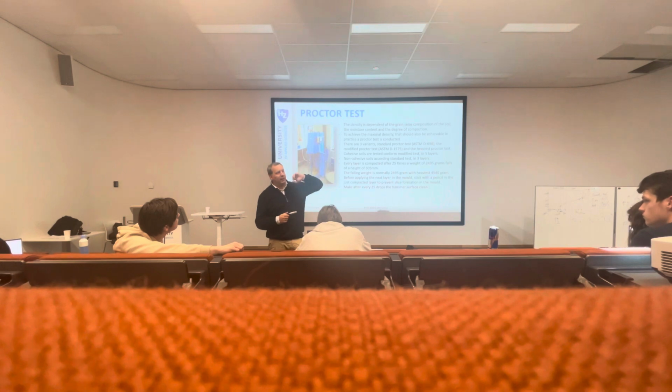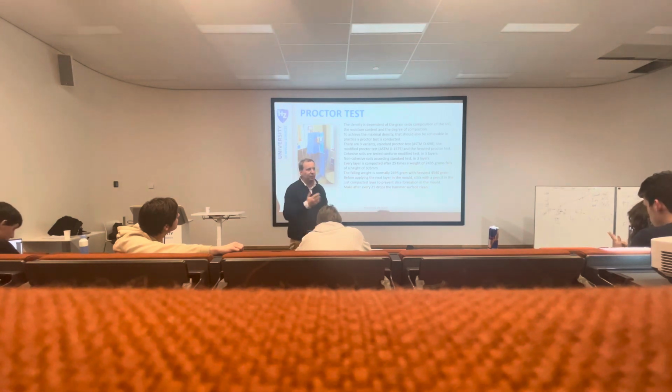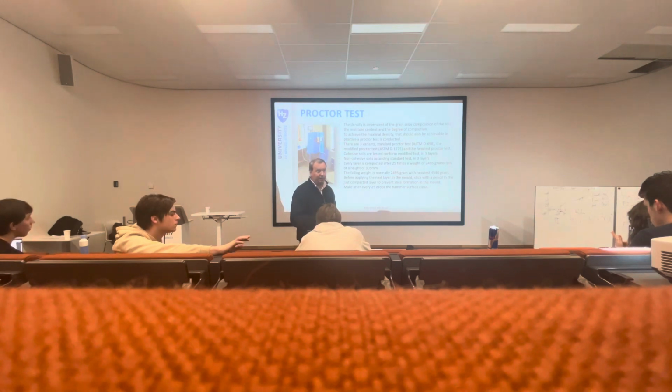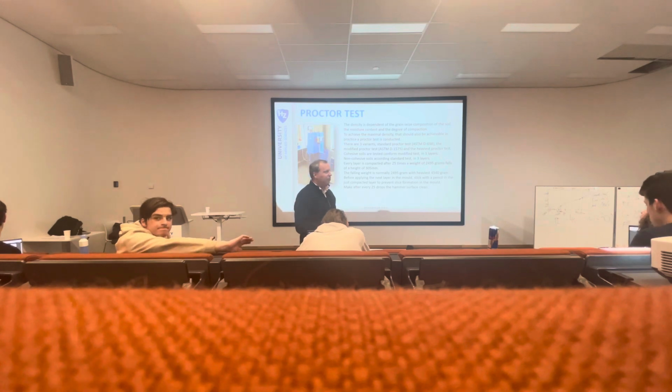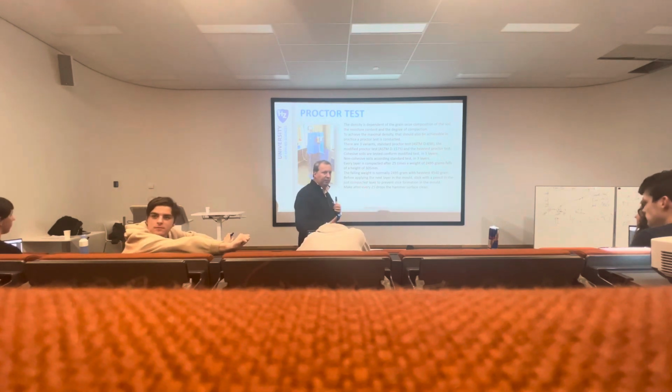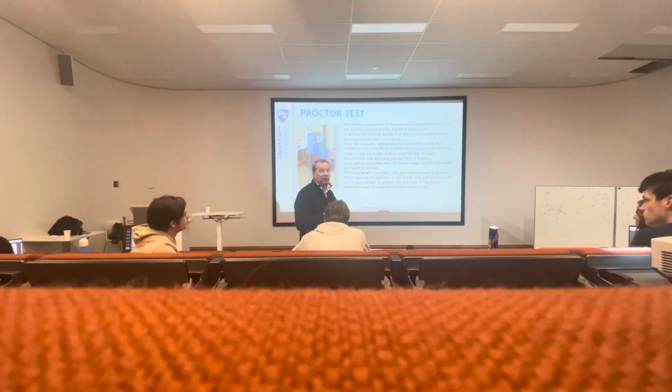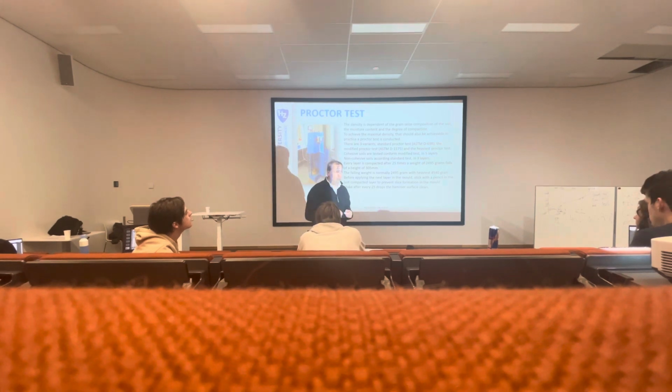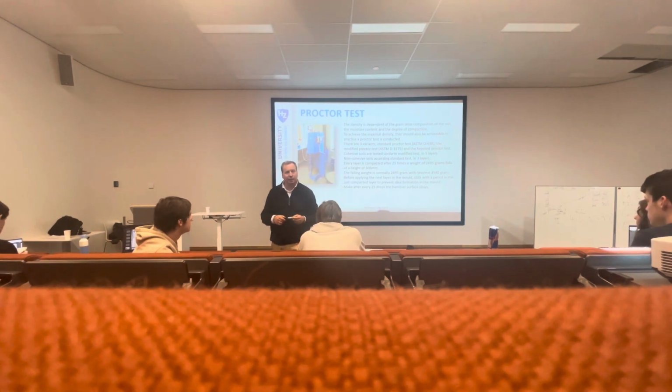Also, you have to check the wind, you have to see the sunshine, because it takes a while between mixing it in and compaction. So you have to think it has to stay open for 1 hour, so add a little bit extra water because it's going to evaporate also a little bit. But don't be bothered with that. Most important is that you know the effect of water on density, and compaction is extremely important. Not compacted soil is a weak soil.